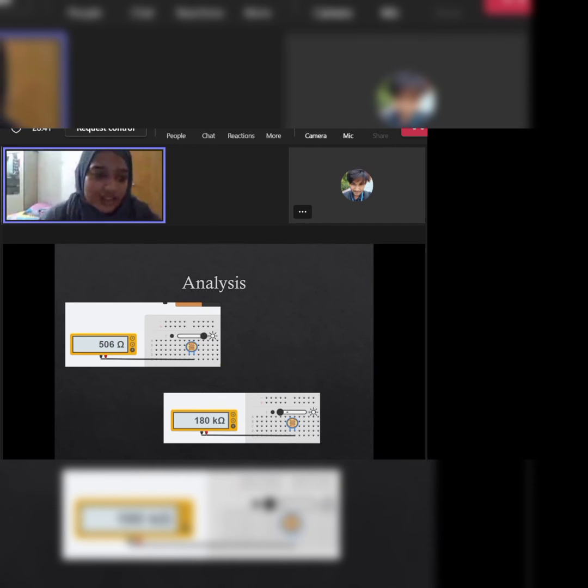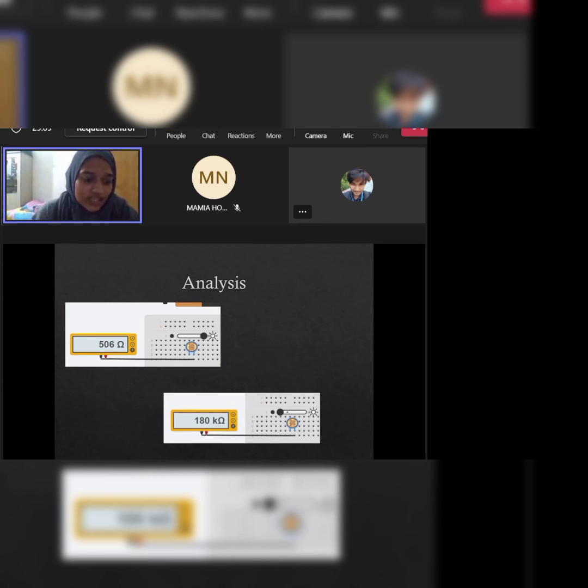My part is analysis. The light sensor can be adjusted so that the output changes if there is an exposure to laser light. The only solution is to convert the change in resistance of the LDR to a change in voltage and pass it to the 555 IC. This conversion can be done using a voltage divider arrangement. In automatic street light circuits, multiple light sensor circuits with different sensitivities can be clubbed together and used as a light meter.